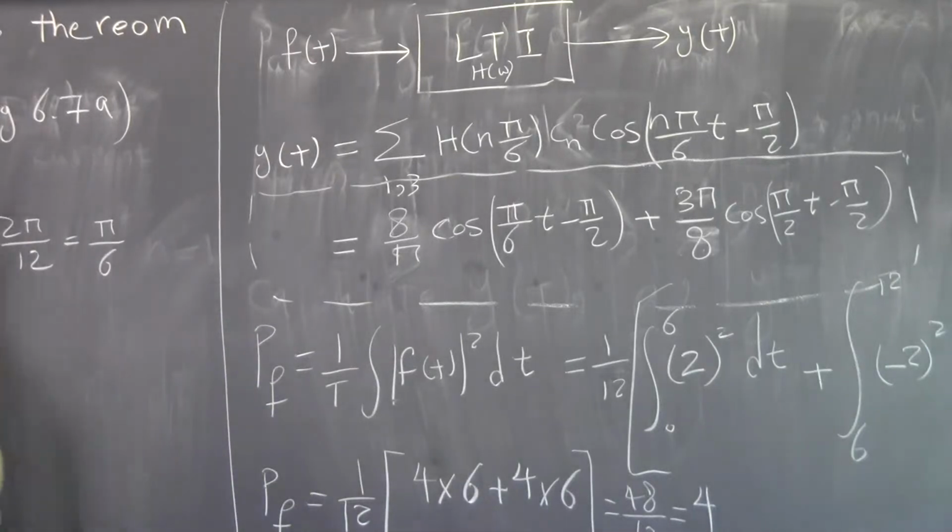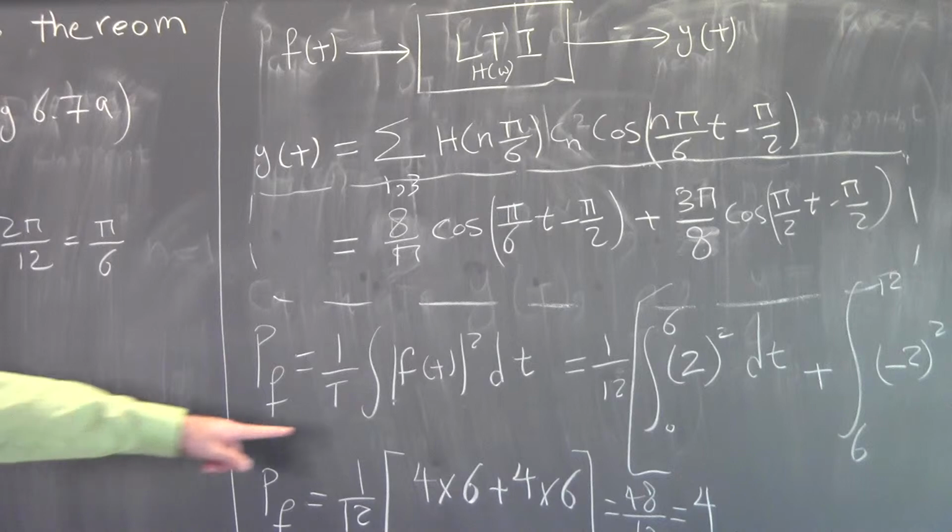Thank you. So what happened? You were telling me what happened to the power. What happened to the energy? Yeah, we filtered it out, right? So part of the energy was in the higher order harmonics. See, we just kept 2 harmonics, 1 and 3, and we discarded the rest. The rest had 0.4 watt of energy, because this is the output, 4 was the input.